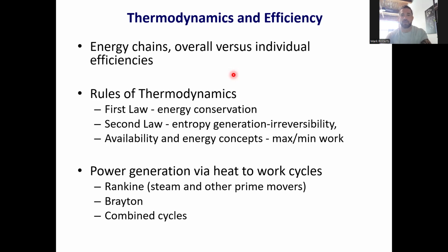The electric vehicles will have an efficiency associated with charging the battery. So we sort of assume that all of the things like friction on the road and the aerodynamics are equal, and we just look at the power source. So for the battery, we have maybe a charging efficiency, so we might lose some power there. But then we have to get that electricity somewhere, and there's going to be an efficiency from the original energy source for producing that in the first place. And so there we might have a charging efficiency of, let's call it 95%, but then the electricity generation might have an efficiency from its original energy source of 30 or 40%.